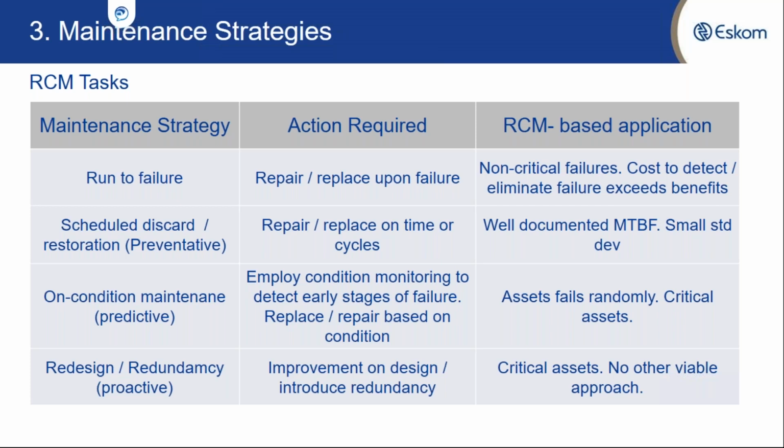And this is applied for non-critical failures, as I've indicated, and where the cost to detect or eliminate failures exceeds the benefits here. Then with the scheduled restoration, we repair or replace on time. This is more like time-based maintenance, and it will be effective if we have great documentation on the mean time between failure studies.